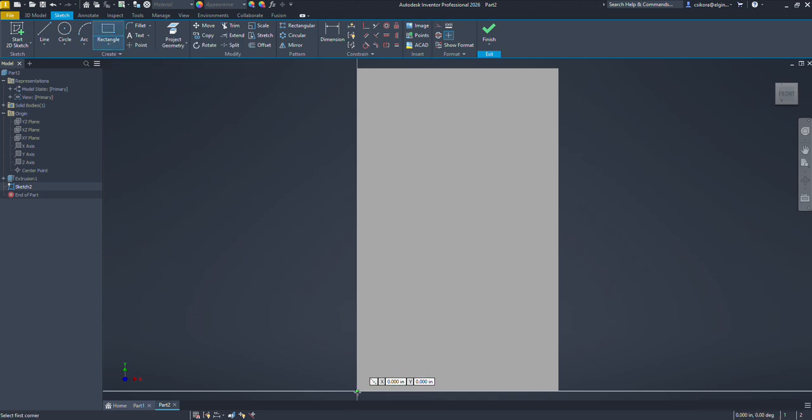Hover your pointer to the lower left corner. When you get the green dot, go ahead and click. Move your pointer to the right. Let it hover and snap in a way. You see the edge on the right highlights in green. That's good, but don't click yet. Just make sure that that edge is snapped, and then you'll see the 3-inch dimension already there.